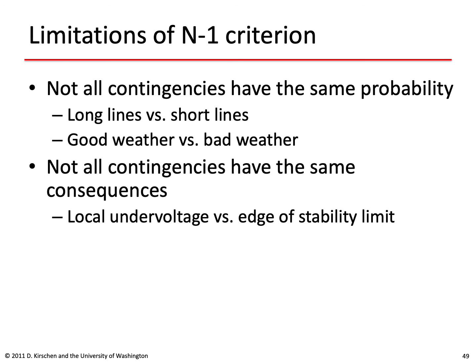Also, not all contingencies are going to have the same consequences. Some contingencies might create a local undervoltage situation, and others could put the system on the edge of stability limits. Therefore, the simplicity of the N-1 criterion does not always translate into a good measure of security.